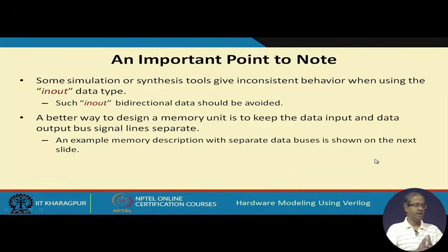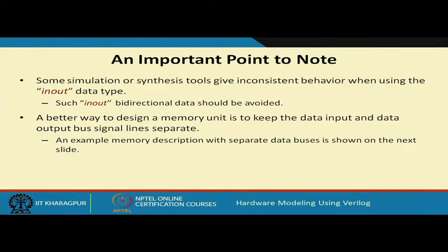Fine. Now, the point that I was making, inout is a data type which is best avoided, because as I said, some simulation or synthesis tools can give inconsistent behavior. So, the experienced designer says that do not use inout data type inside a Verilog code.